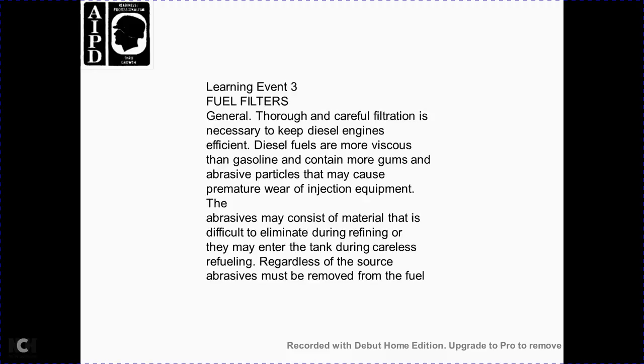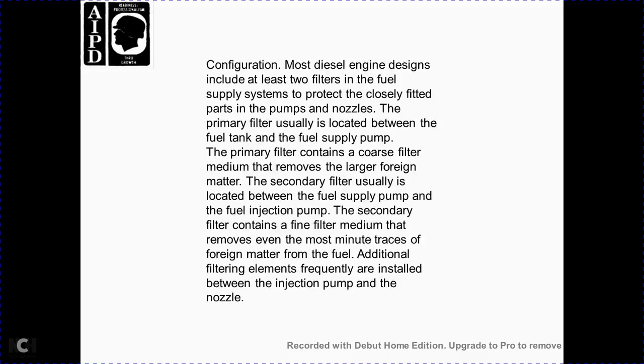Learning event 3, fuel filters. Generally, careful filtration is necessary to keep the diesel engine efficient. Diesel fuels are more viscous, but gasoline contains more gums. Abrasive particles cause premature wear of the injection equipment. The abrasive may consist of material that is difficult to eliminate during refining, or may enter the tank during careless refueling. Regardless of the source, the abrasive must be removed from the fuel.